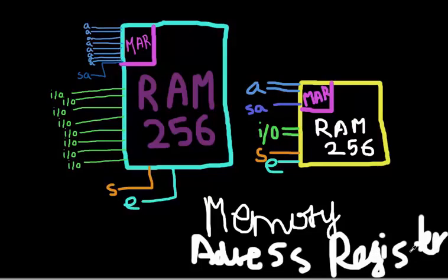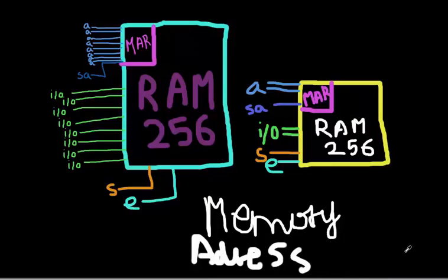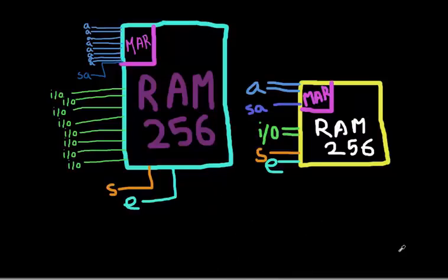The memory address register, as we have seen, selects a particular byte by turning on any one wire of each of the two decoders, and where they intersect we get the selected byte to use. So that is what the memory address register is. It just registers one of the 256 bytes available so it can be used somewhere else, and that can be passed along the bus.